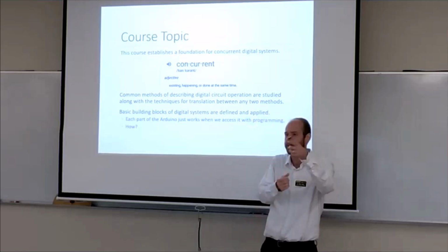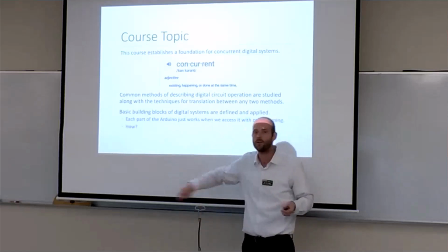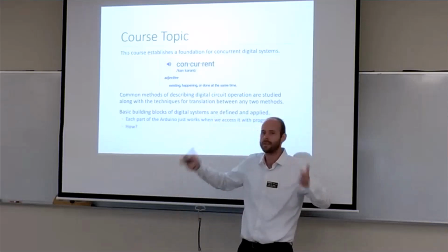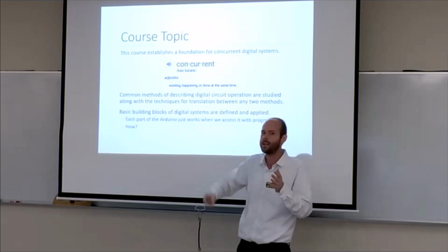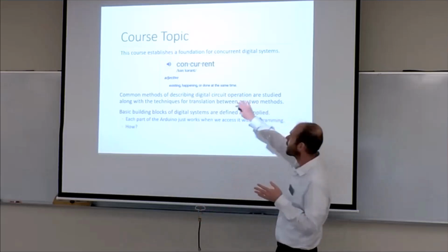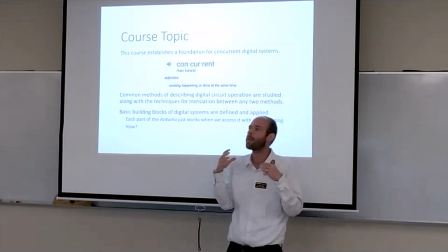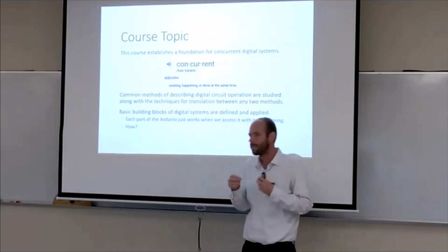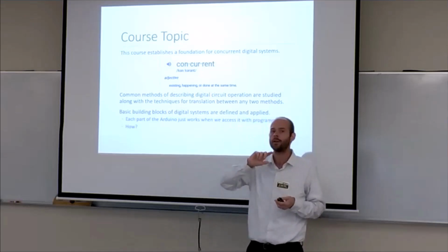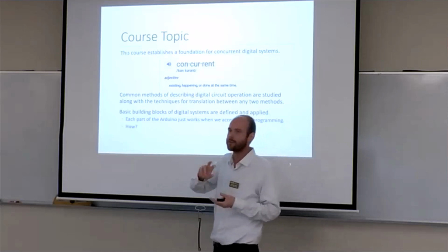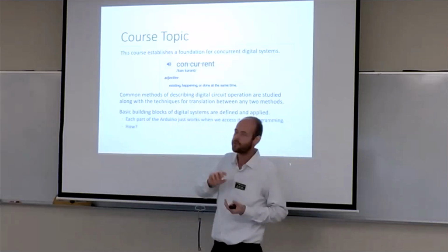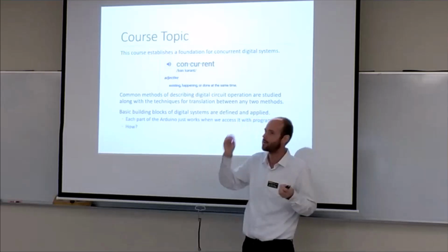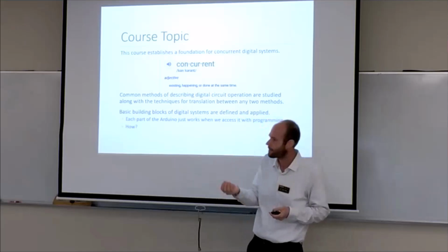So if I set a ball on a ramp and let it go and it rolls down, maybe goes around a loop if you've got a setup with a track, those actions happen because of the physical setup. It's not a sequential initiation of those actions. And so when we talk about concurrent digital systems, we're talking about systems that are driven by a continuous clock signal, and that happen due to flags, to registers, which are a 1 or 0 bit being energized or not energized. The state of the circuit is what drives the action, not sequentially running C code. And so that's the big difference in our lab setup as well.